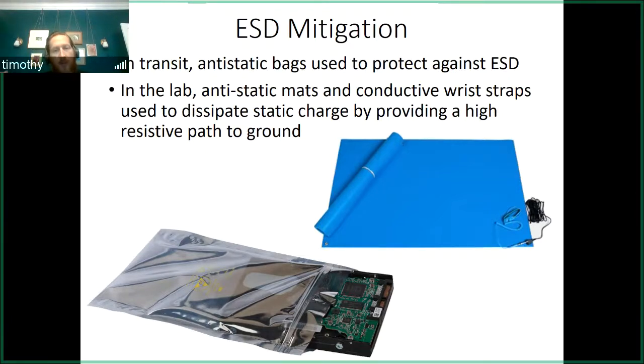A lot of times with the electronic equipment that we're using, as long as you have the mat and as long as you touch that ground terminal before you start messing with it, you should be pretty good. That discharges the static. Here is an anti-static bag. Inside that anti-static bag, you would want to put your electronic devices to transport them.